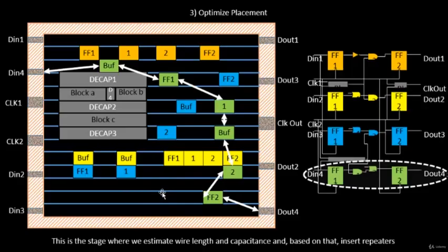Okay, so based on the frequency, or based on the specifications that have been given to us, and we'll also note down some specifications, we have to check whether this placement condition is meeting those specifications. If not, then we have to see what we can do, because if it doesn't meet at this stage, it's bound to get bad when we go to further stages of placement and route, or basically the route stage. So let's do the setup timing analysis for ideal clocks in the next video.